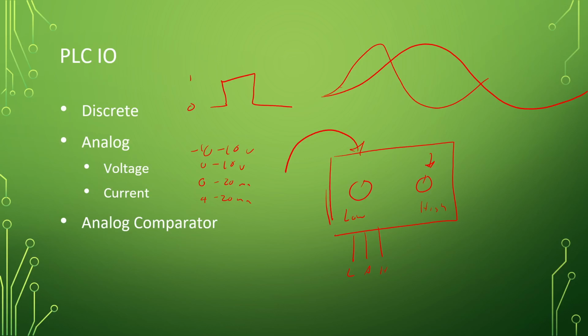Now the benefit here is you can use just one wire, or you can use all 3 of those wires. You don't have to wire everything up to your PLC. You could say, I don't care if it's low or high, all I care about is is it an acceptable height, and you could program that. Again, for a pressure system with this, you could say, whenever this low signal becomes true, turn the compressor on. Whenever the high one becomes true, turn the compressor off. We don't care about acceptable. Just ignore the acceptable. So you have options there, but it's a nice little simple device that will take an analog input and convert it to a digital output, which is really nice, or a discrete output.